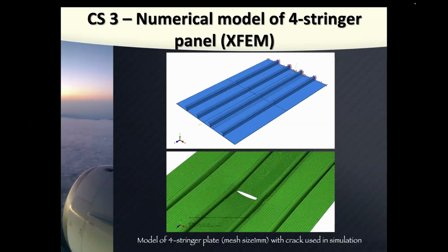And fortunately, this guy gave me an Excel file from the machine with all these parameters recorded by the machine they used in the experiment. And then first I made this model. This is the model, of course, in Abaqus, where I used a mesh size of 1 millimeter, okay, which is a very, very dense mesh.